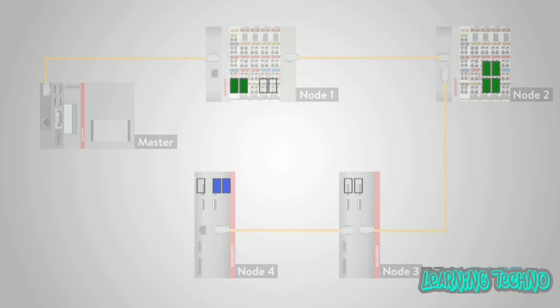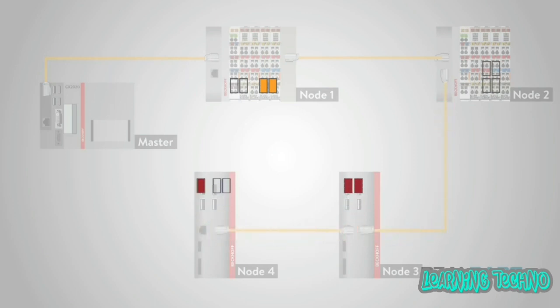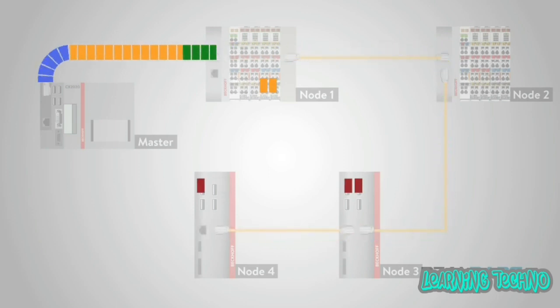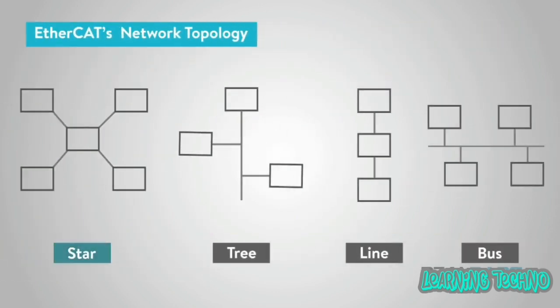Yet another advantage comes in the form of network topology. Many of the different network topologies may be used within an EtherCAT network. Because it utilizes Ethernet's full duplex layers, the EtherCAT slave will automatically return the frame to the master when an open port is detected downstream, essentially self-terminating. Ethernet star topology is simple and can be used, but EtherCAT networks can extend well beyond that with a tree, line, etc. It can also be used in a fieldbus type system using Ethernet hardware, giving incredible flexibility for your EtherCAT network.